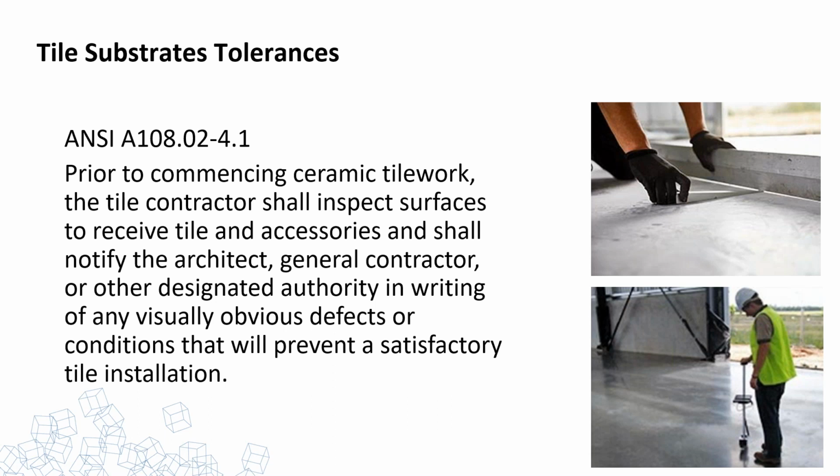Some other ANSI language, it's, in my opinion, very favorable to the tile contractors. ANSI A108.02: prior to commencing ceramic tile work, the tile contractor shall inspect surfaces to receive tile and accessories and shall notify the architect, general contractor, and other designated authority in writing of any visually obvious defects or conditions that may prevent a satisfactory tile installation. That's important. Take that step. Make sure that you point out the issues.